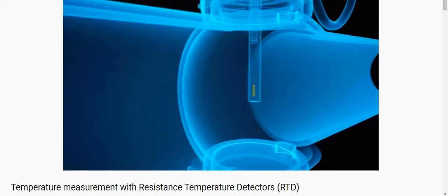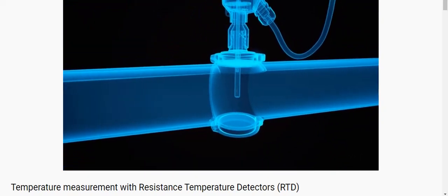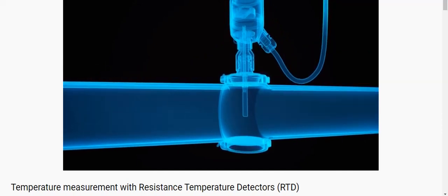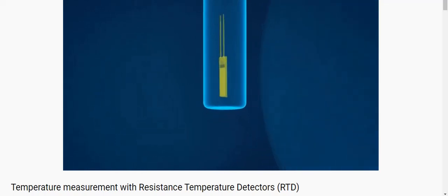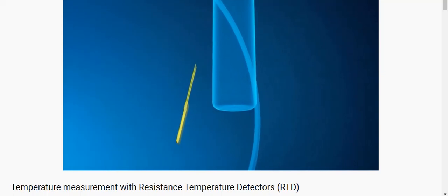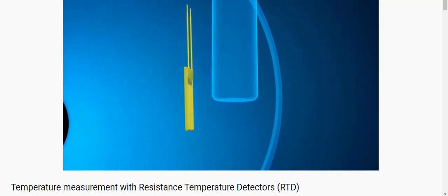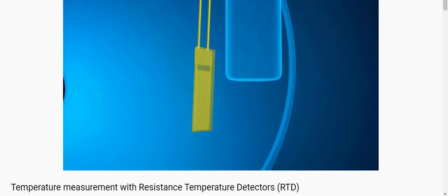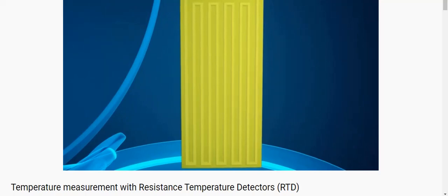Thermometers generally consist of a thermowell, which houses a rod-shaped tube as the main element. This is the measuring insert, and it has a temperature-sensitive sensor fitted in its tip. Nowadays, resistance sensors based on thin film technology are the most commonly used. Platinum resistors, known as PT100 sensors, are mostly used. A very thin conductive track made from the precious metal platinum is deposited onto a ceramic substrate.